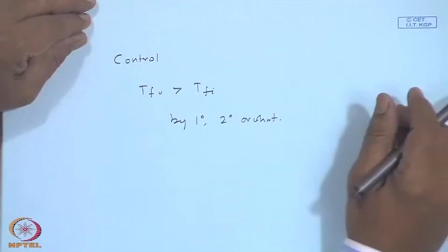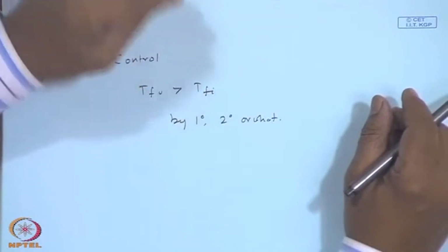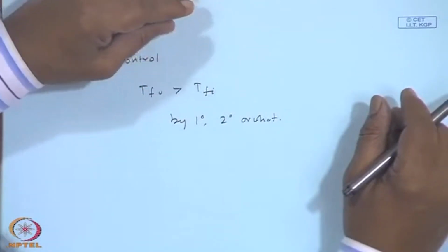So, if you put the thermostat in the control, actually you will find that it is turning off or turning on the pump with 5 degrees of bandwidth, compared to another control which may have a bandwidth of only 1 degree. Okay. So, which one is better will depend upon again your utilization and applicability.